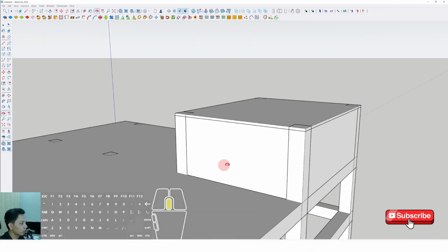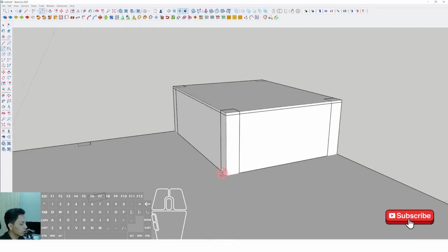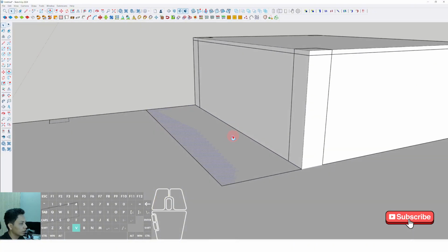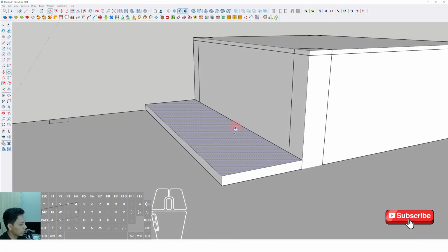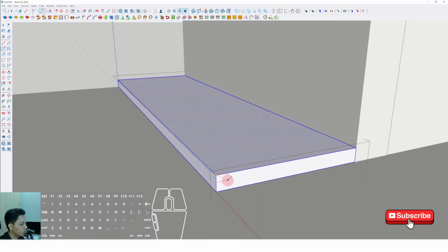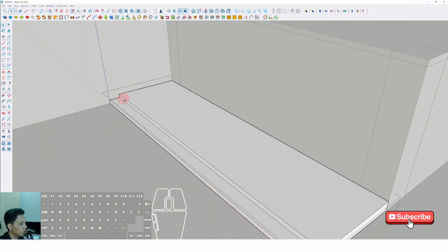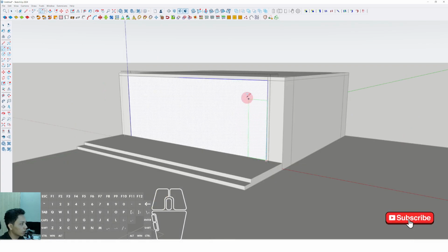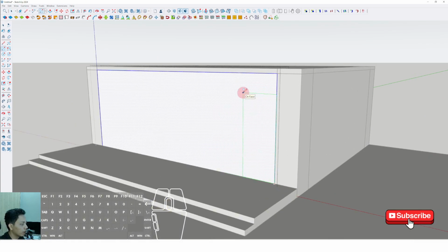Then now we can draw the floor of the maintenance access. Maybe we can draw this floor area in here, but then we can give the thickness around 300 millimeter. Then we can make it group, and then we can draw the small step for the small hallway in this area. Then we can draw the door with the standard height, maybe around 2.2 meter.